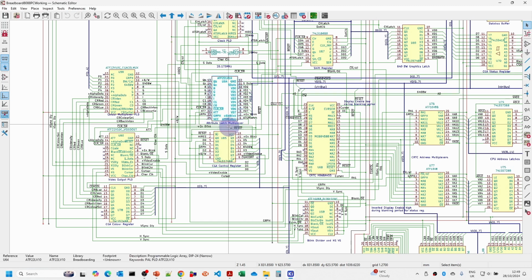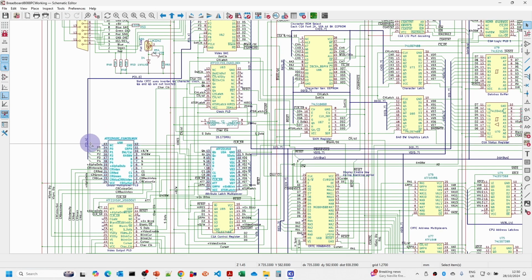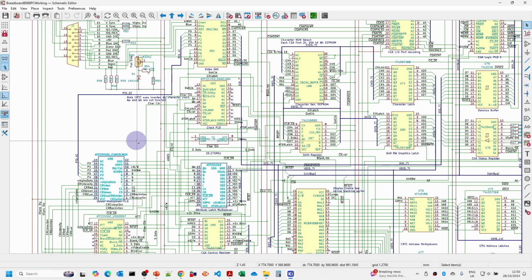this is the character latch multiplexer. It takes the foreground and background colours, and we'll use the S dots to determine if we're showing the foreground or background colour. We'll also divide up the medium res graphics based on the clock signal QCQB, which goes through 4 cycles every character, and that will provide us with the C1 and C0 outputs 4 times per character. That then goes into this PLD, which combines the various outputs and produces the output to go off to the video digital analog converter up there.